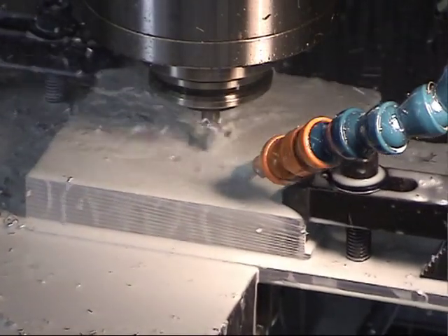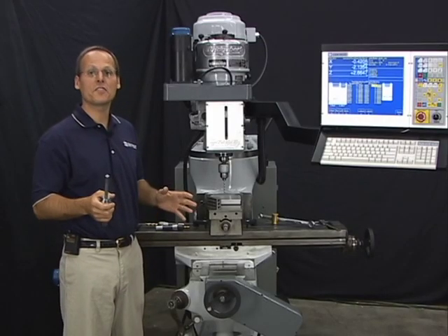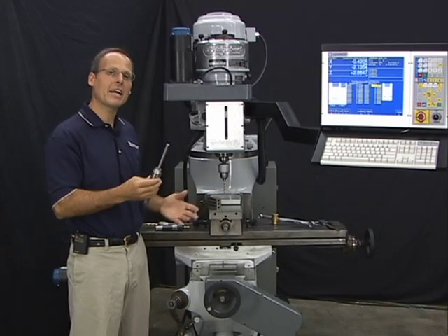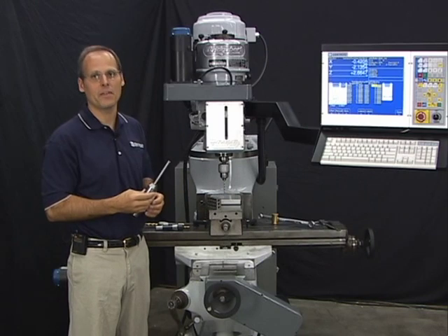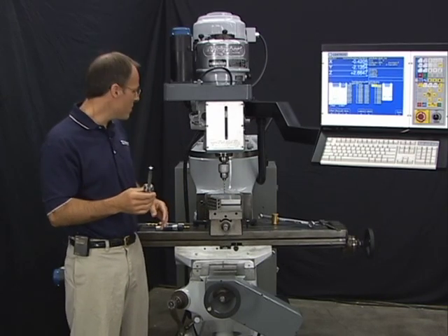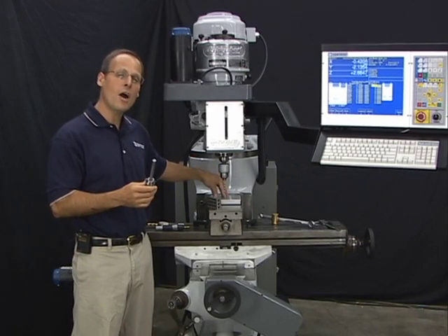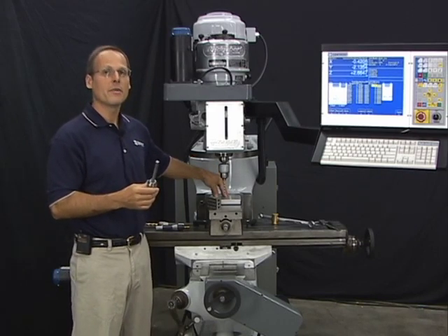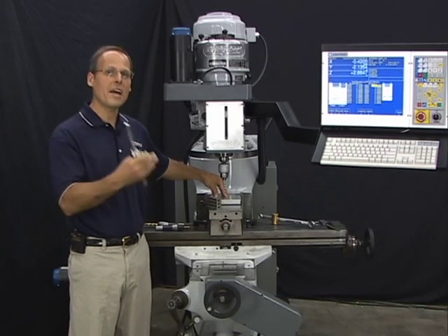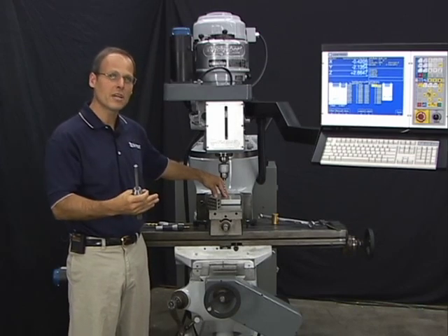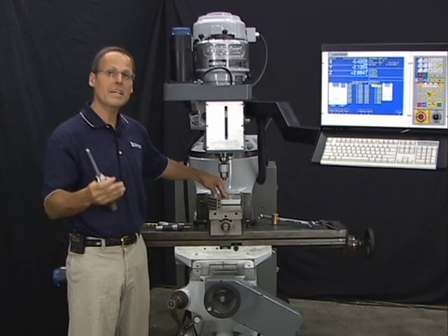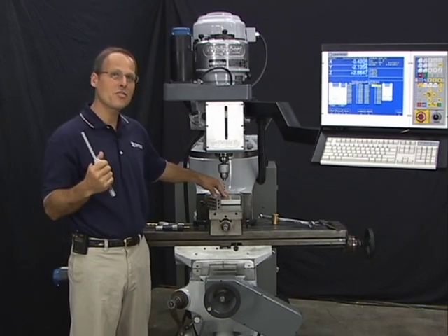Now some folks that are watching this training video that have some prior CNC experience might think that using a reference tool is like adding an extra step to setting your tool height offset values. When in reality it's really a time saver. Because the old method of setting all your tool heights off the top of the work may work, but what it does is it requires you then to reset or remeasure those tools for every single job that you do, even if they're the same tools that you just got done using.